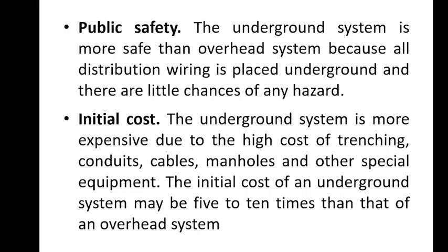Underground systems on the other hand require extensive civil work such as trenching. You need to dig the ground and make some trench, and installation of conduits, specialized cables, and manholes, which makes their initial investment significantly higher than the overhead constructions, often 5 to 10 times more than overhead systems.